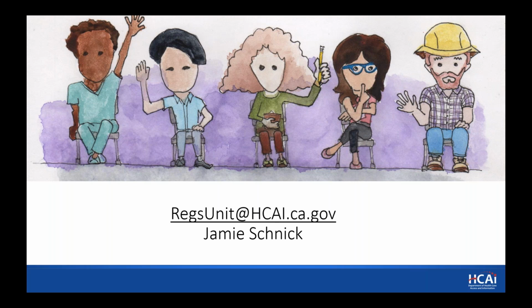So to answer the question about is this required over transformers? The answer is no. To answer the question about am I allowed to have sprinkler piping that's at 6 foot 6 inches above the equipment, that is code permissible. I would recommend that you have a drip pan so that you don't have the issue of water getting on your electric equipment, but it's not a code requirement.